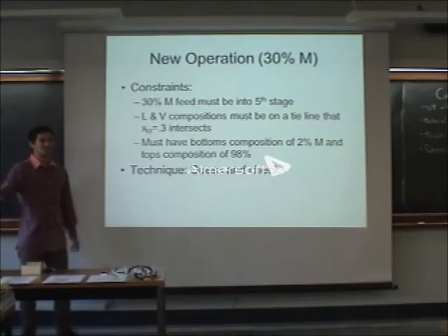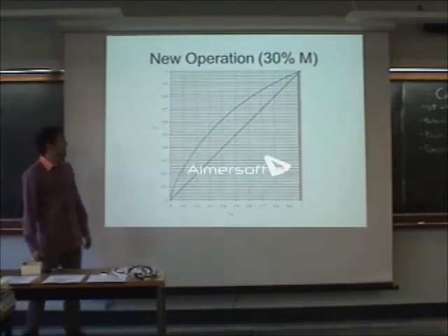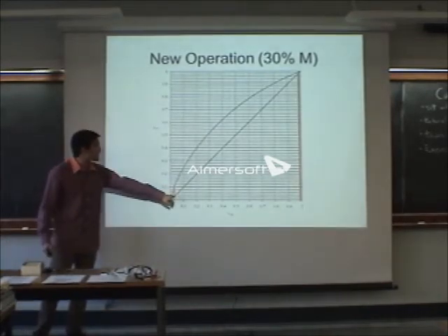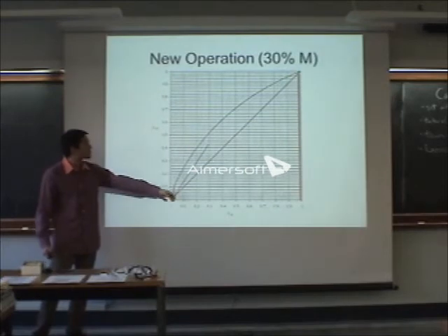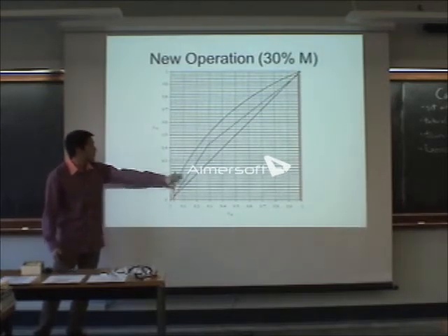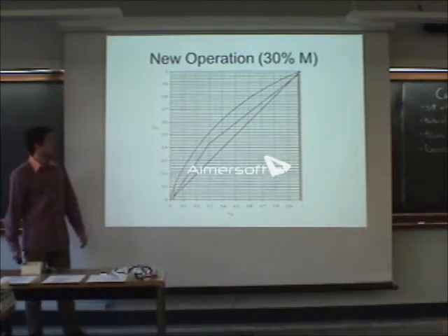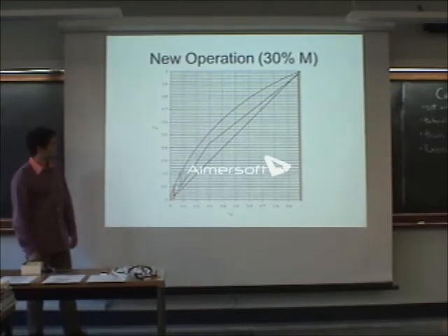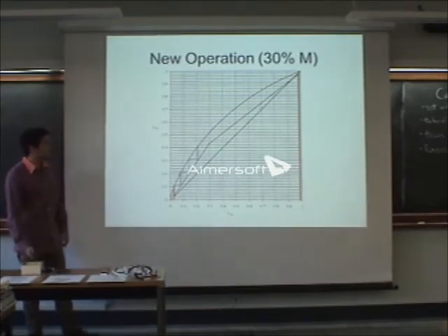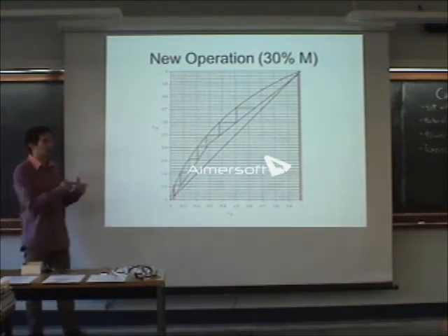You'll get better at this throughout the years, don't worry. So we're going to make the first guess. We know these two endpoints on the operating line, and then let's just try some new rectifying and stripping operating lines and see what happens. So we still want to get 11 stages, and we still want the fifth stage to be where the operating lines change.